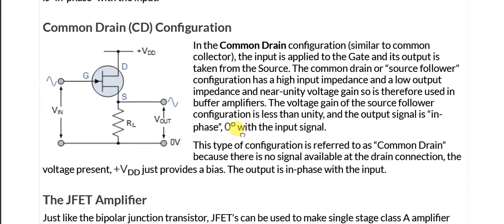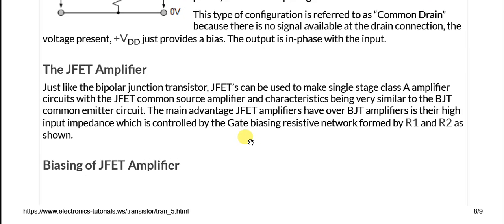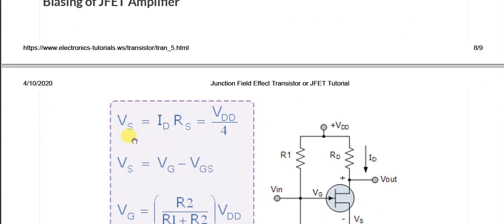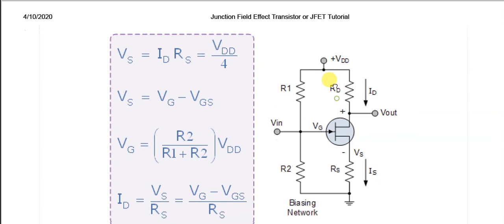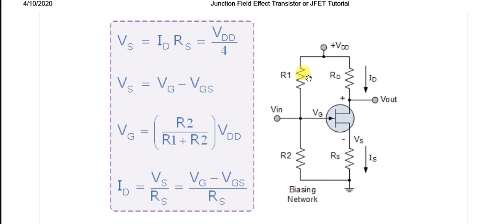Now the JFET as an amplifier, we have the relevant relations. Again, this is the self bias. You can see the 4 resistors. The same techniques are applied as we have studied in the BJT transistor amplifier. So that is the common source amplifier, where the common terminal is the source. We have an input resistor which is controlling the gate voltage, and this is the drain current. Obviously the polarity has to be kept accordingly, the gate reverse biased, so it can produce a reverse bias field.